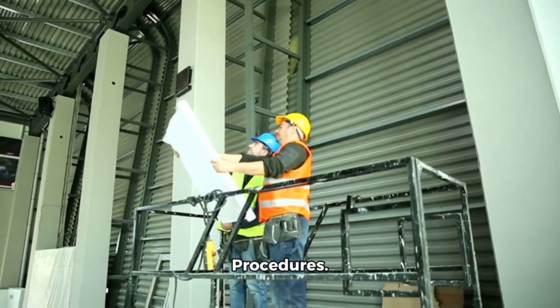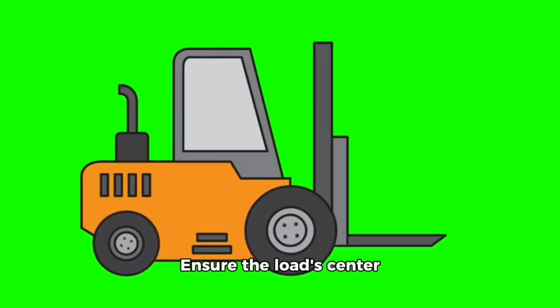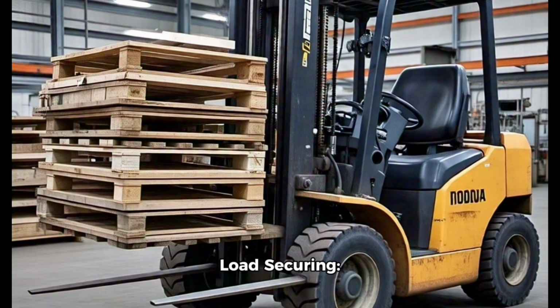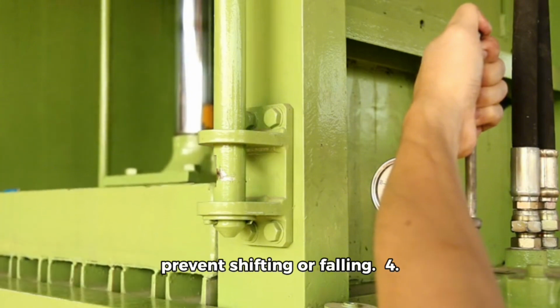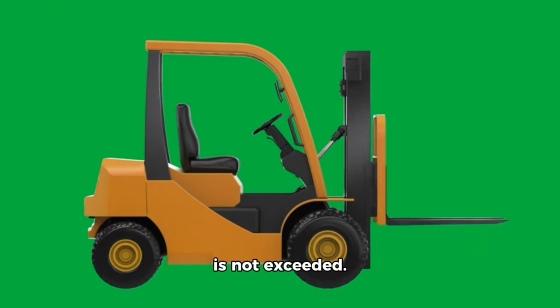Safe load handling procedures. 1. Center of gravity. Ensure the load's center of gravity is within the forklift's stability triangle. 2. Load balance. Ensure the load is properly balanced on the forks. 3. Load securing. Ensure the load is properly secured to prevent shifting or falling. 4. Forklift capacity. Ensure the forklift's capacity is not exceeded.